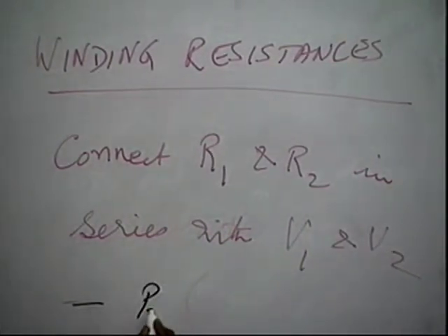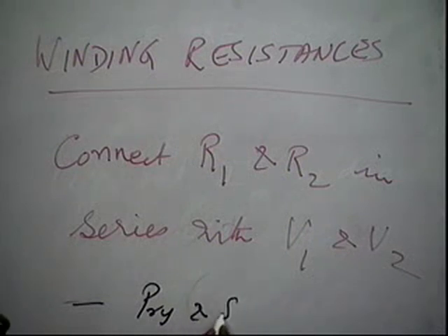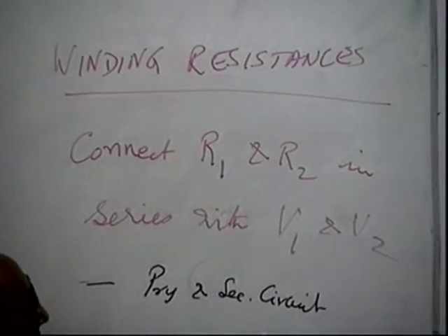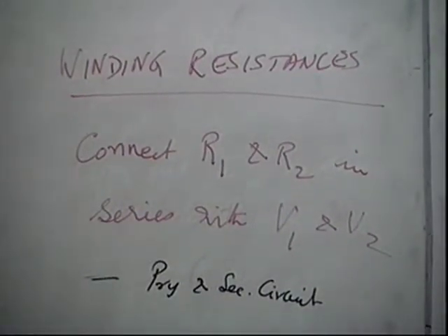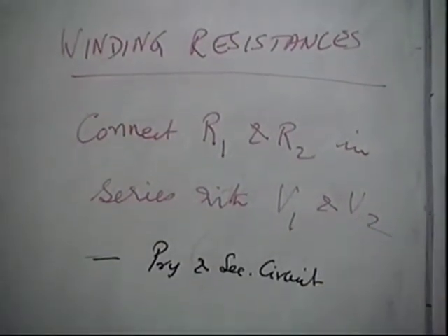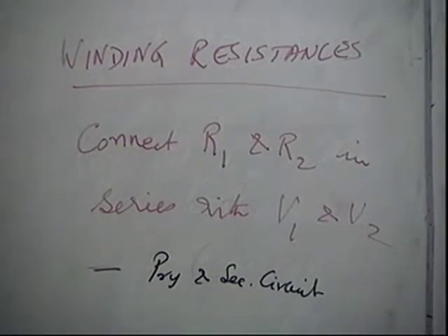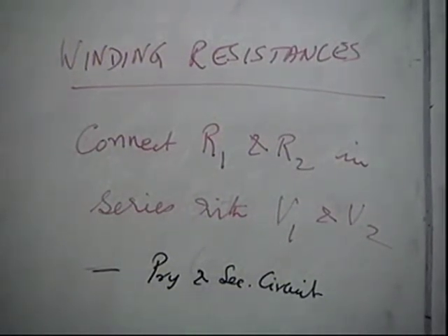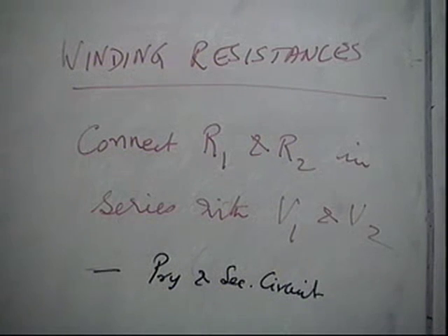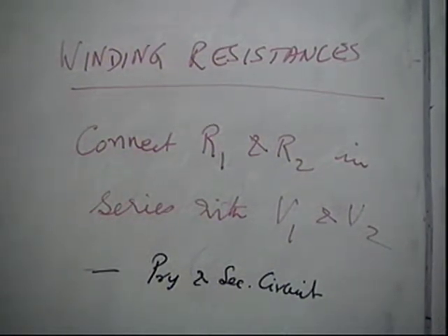Yes. So that IC was due to some finite resistance of the core. IC is the current component such that V into IC gives the power. So no, that IC flows in the coil, not in the core. It is drawn from the supply. Whenever something is drawn from the supply, it doesn't go into the core. Okay, but that is to compensate for the losses in the core, for hysteresis and eddy current.